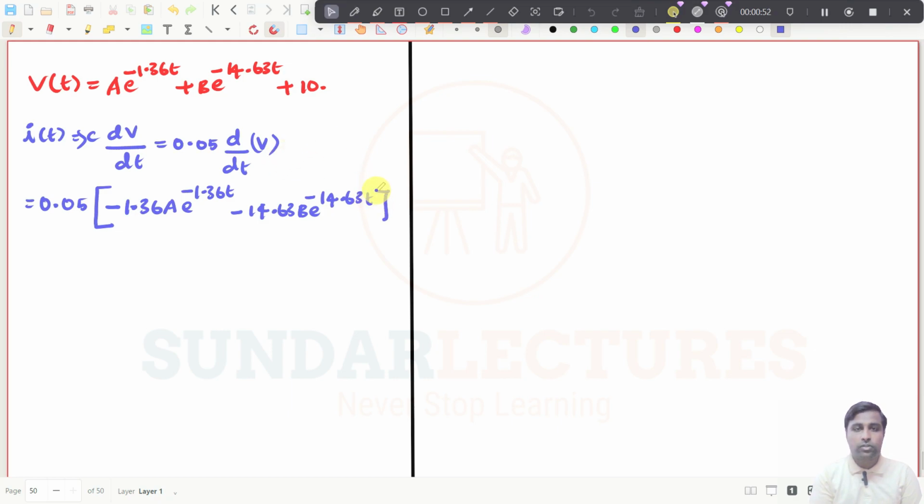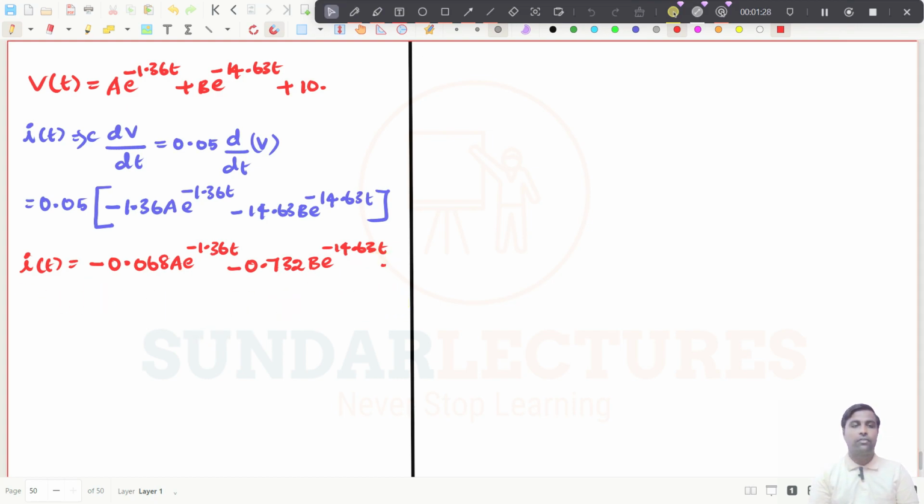Plus 10 will be 0 since it is a constant, and if I further simplify this, the C dV/dt value becomes I of t. I of t can be written as, I just multiply this inside, you will get minus 0.068 a e power minus 1.36t, and then this value will be minus 0.732 b e power minus 14.63t. And now this is the value of I of t.